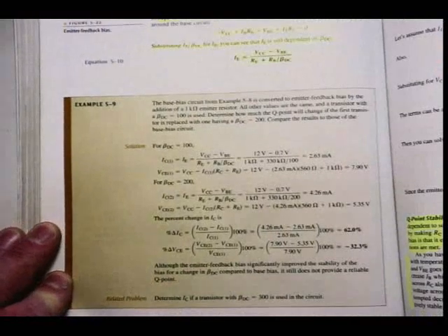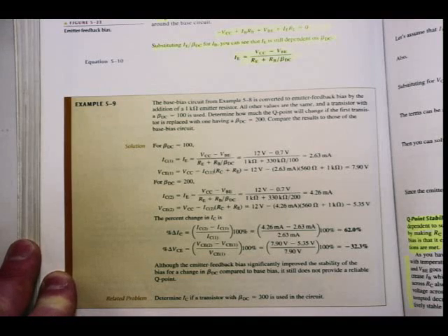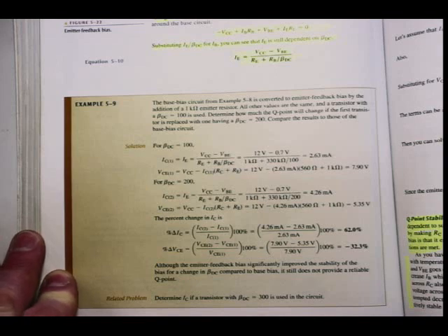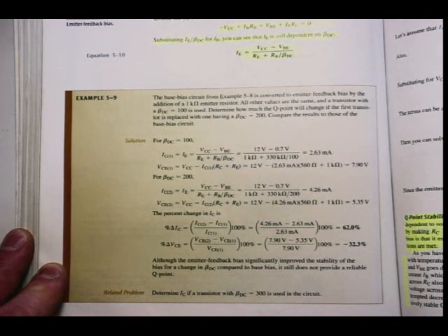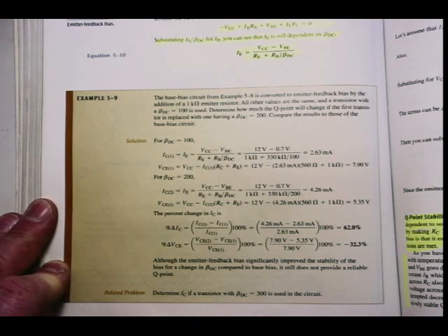Anyway, an example here, example 5.9. The base bias circuit from example 5.8 is now converted to emitter feedback biasing by adding a 1 kilo ohm emitter resistor. All other values are the same, and a transistor with a beta DC of 100 is used. Determine how much the Q point will change if the first transistor is replaced with the one having a beta DC of 200. Compare the result to those of the base biasing circuit so that we can see was there any improvement. So for beta DC of 100, I got